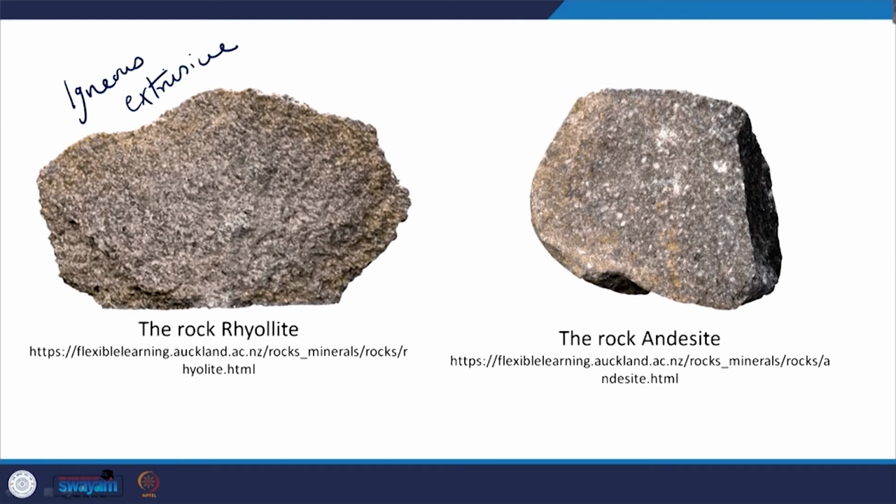Color is variable, but in general it is a light colored rock. The texture is usually porphyritic, but it can be aphanitic also. Silica content in this case is 69 to 77%. This rock can be used as aggregate or fill in the construction and highway industry. Pumice is used as an abrasive, especially in the cosmetic industry, and can also be incorporated into lightweight building materials.